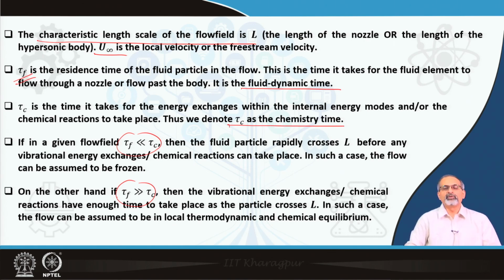and therefore, to be on the safer side, it would be reasonable to solve the flow as a non-equilibrium one, and then try to figure out in which regions it is predominantly behaving like a frozen one, behaving like an equilibrium one, and also behaving like a non-equilibrium one as a mixed regime.